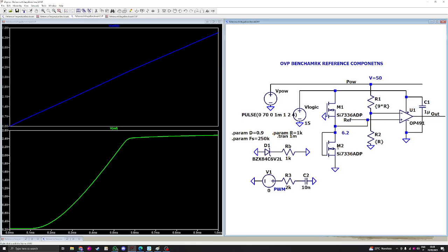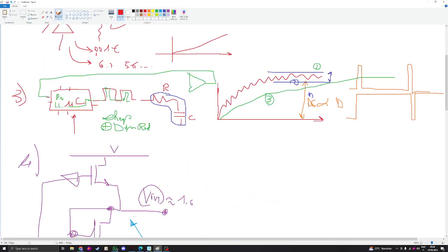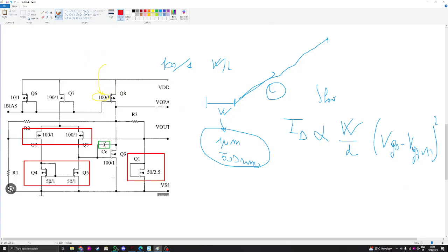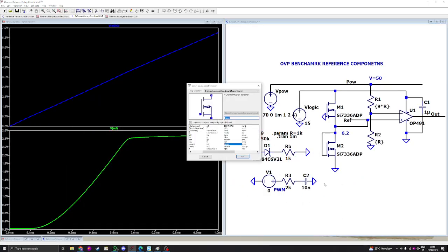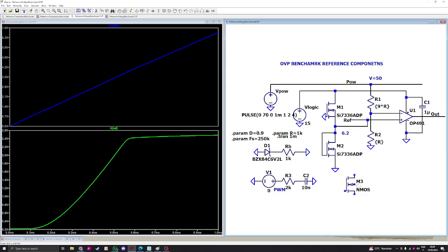It's almost never used as a discrete MOSFET, but as I told you before, it is used in integrated solutions like this one. There is no reason to simulate this. You can have a more appropriate simulation if you use the NMOS4. I did something like that in the past. As you can see, you can set the length, the width, the area, the end area, but you have to know your stuff, because if you just short like this, okay, we can try.